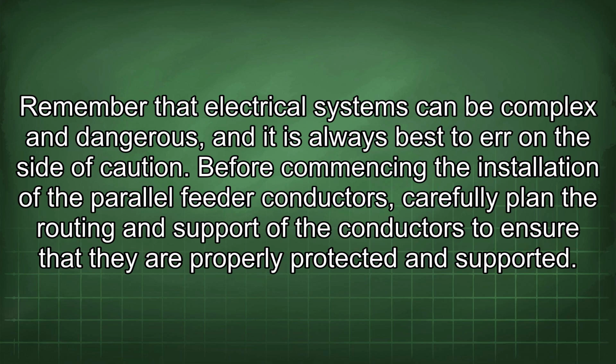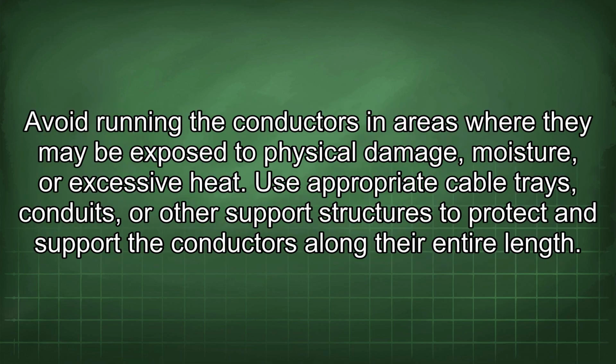Before commencing the installation of the parallel feeder conductors, carefully plan the routing and support of the conductors to ensure that they are properly protected and supported. Avoid running the conductors in areas where they may be exposed to physical damage, moisture, or excessive heat. Use appropriate cable trays, conduits, or other support structures to protect and support the conductors along their entire length.